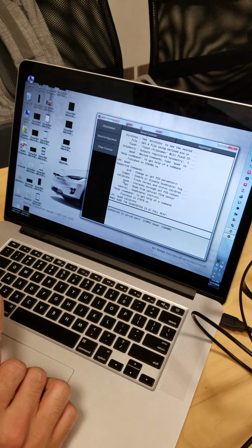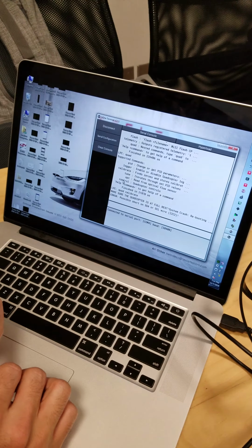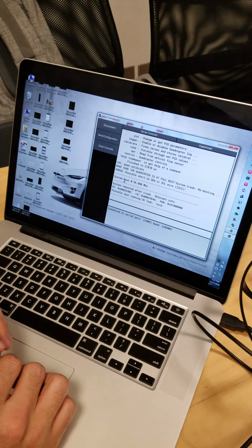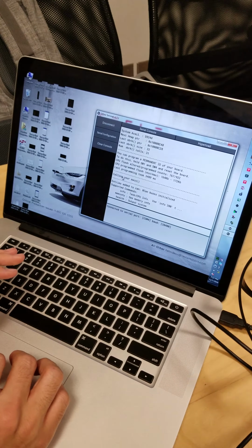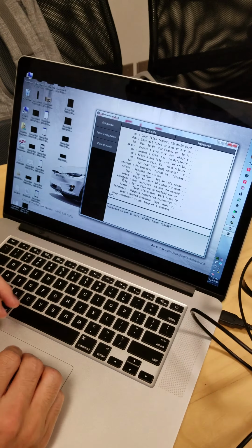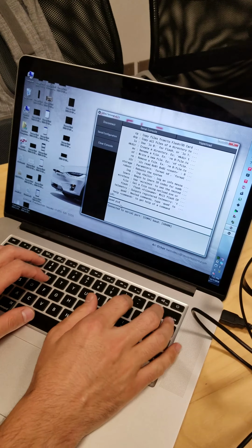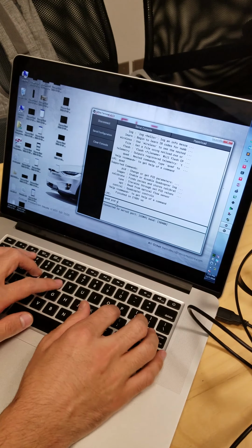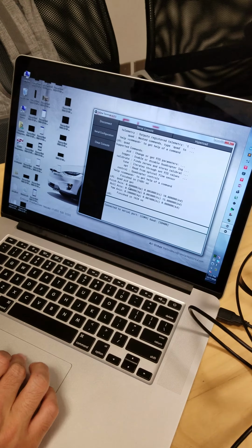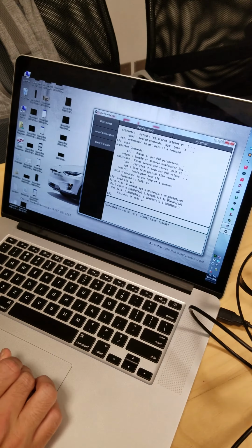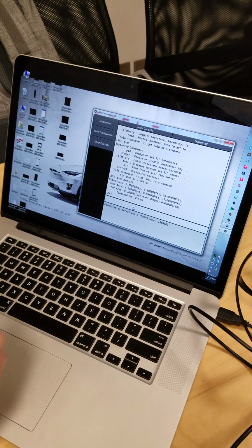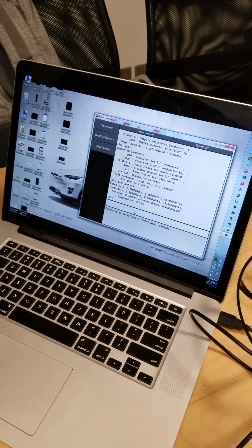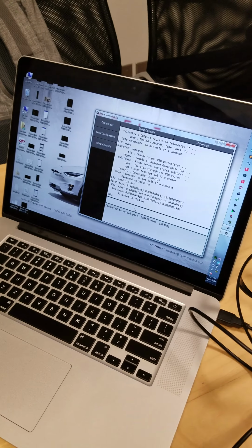So we can set quad calibrate, and what it's doing right now is calibrating the sensors and resetting the sensor values to 0, so that right now the sensor angles are offset 0. And here other commands that we have are quad PID and get. So right now we have our PID gain coefficients readily available, and we can basically read and write to NVRAM.